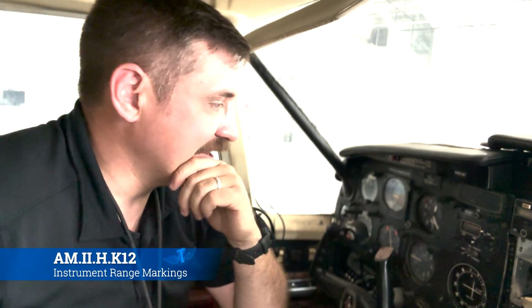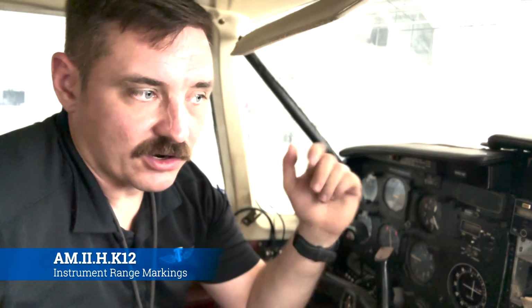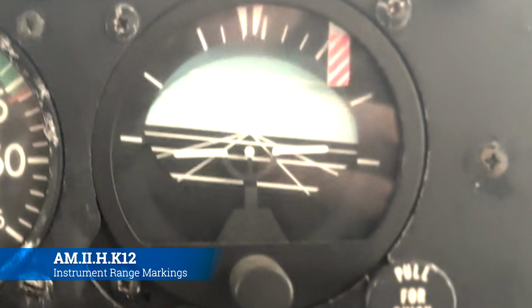Other markings that are not necessarily indicated as good or bad are like our artificial horizon. It will tell us basically what degree the airplane's wing is pitched up, or where the nose is at. The wings on the little airplane in the middle of the artificial horizon will indicate the right and left wing. The dot on the horizon will indicate where the nose is pitched up, and then the lines on the backdrop and around the edges of it correspond to different degrees of flight attitude, be it pitched over one way or pitched over the other way, and so on and so forth.